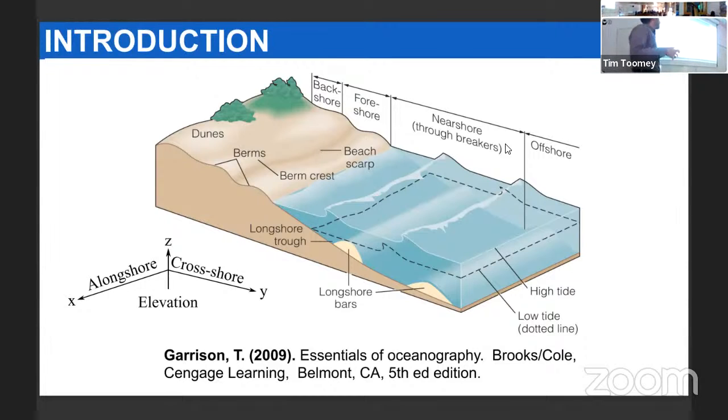So, for example, if you go to the same beach in summer and then in winter, or before a storm and after a storm, you may see that the shape changes. When strong incoming waves come, they tend to scratch this profile here and generate this staircase, what we call scarps, and then it transports the sediment beneath the surface and generates these bars.